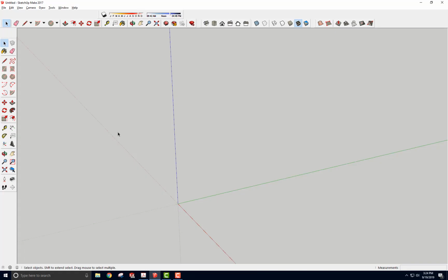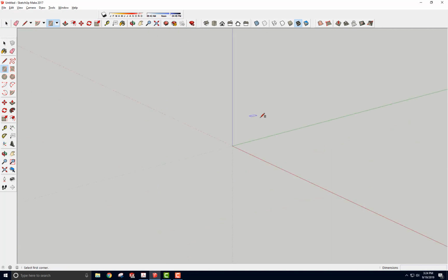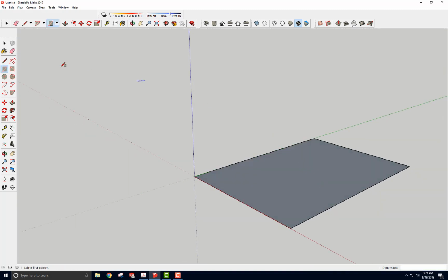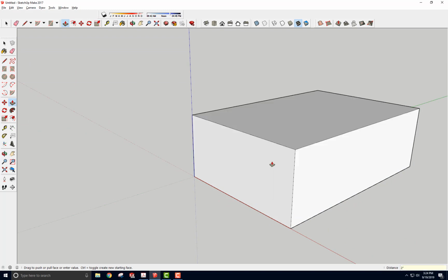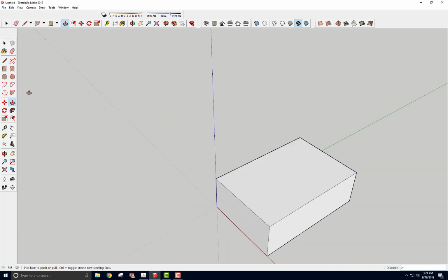So I'm going to go back to SketchUp here. I'm going to click on View Extend so it centers this, and create a 4x6 base like this. So type in 4,6. Right, there it is. I'm going to bring this up 2 inches, and then create in the top surface here a couple of rectangles to work with.